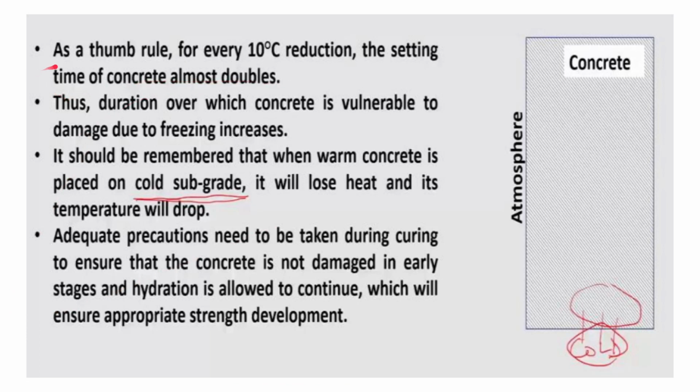As we saw, as a thumb rule, for every 10 degrees centigrade reduction, the setting time of concrete almost doubles. Thus the duration over which concrete is vulnerable to damage due to freezing increases. The more the duration over which the concrete is frozen, the more the damage automatically increases, because of the increase in setting time.